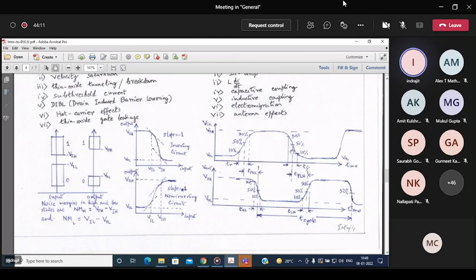Similarly, when the signal goes down, it is like that. And similarly, we have the output voltage. For an inverter, if this is the input voltage pattern, this will be the likely output voltage pattern. Not always, mind you, but typically if the signal transition is smooth and the operation of the circuitry is more or less acceptable, then we see this kind of trend.